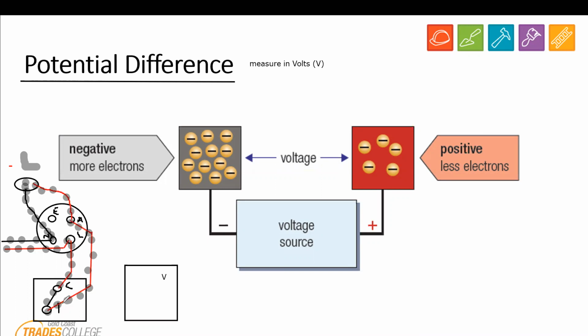If I know that this circuit is on, if I put my black lead in number 1, and then I put my red lead in there, we know that this circuit is switched on. We know the light is on. An untrained person would expect to see the voltage in the circuit here. But the dangerous thing is you're going to see 0 at that point. All right. Why am I going to see 0? Okay, and I'm going to draw another one in before I tell you the answer there.